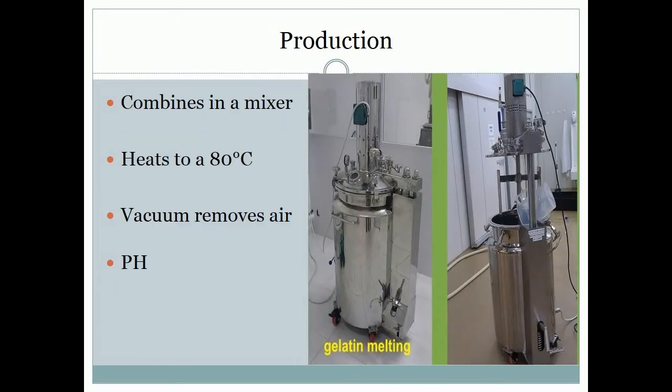You need a water bath type gelatin tank used for melting, mixing and storing the gelatin. The gelatin melting tank has the advantage of compact structure, stable transmission and stable running performance. The mixing and stirring process is operated through connecting loop coupling and is composed of dual split agitators with stable transmission and better homogenization effect. The body includes 3 layers, including the tank liner, heating jacket and heat preservation layer.